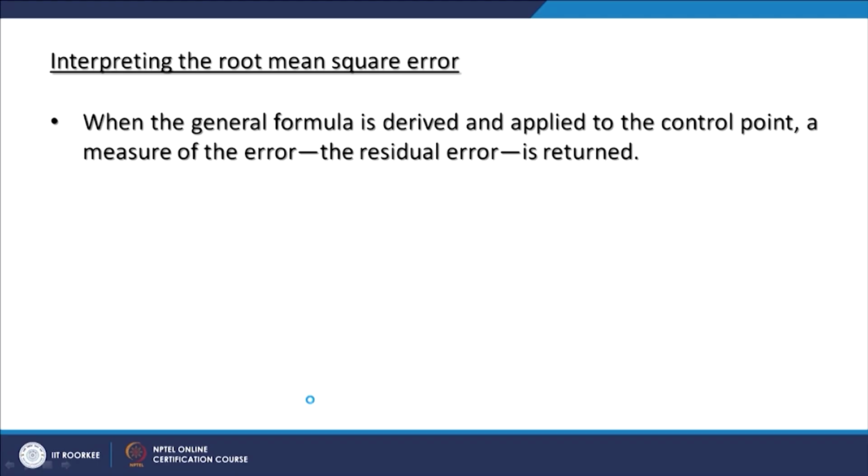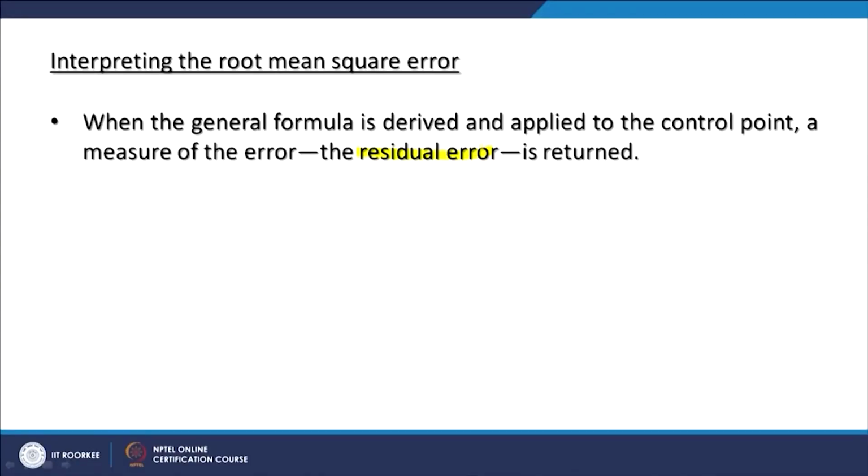Now the software has become very smart, and modern software like ArcGIS or others, while doing this geometric registration, that means identifying ground control points and registering with the master map, will keep giving you the residual error, both the total one and also for individual ground control points.